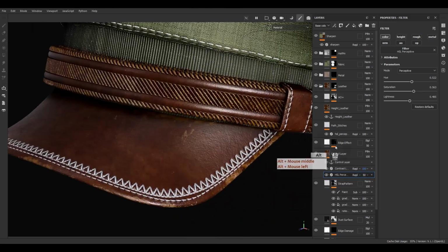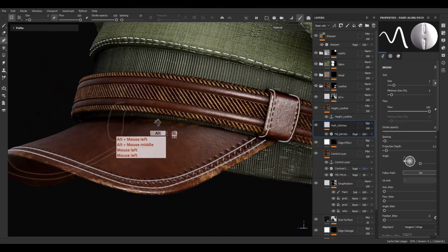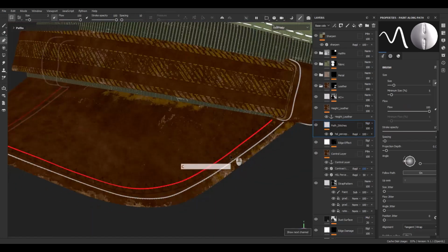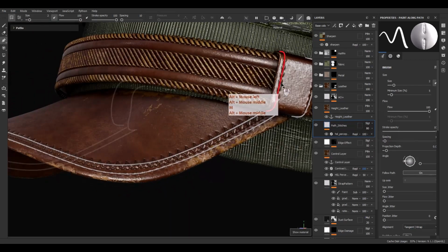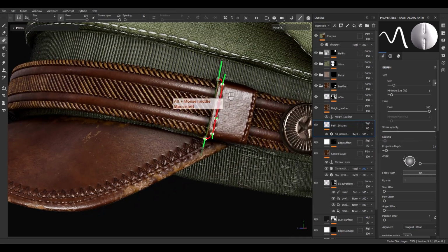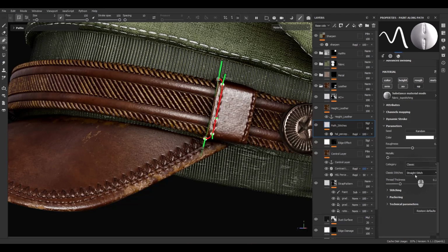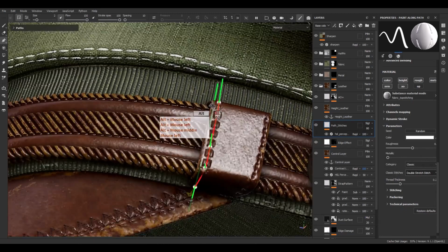And I'm going to use soft light on the blending mode for the stitches. Yeah, it's so much better to have something like this. Okay, and we can decrease the opacity amount to something like 80. That's it. And for this kind of stitches over here, I can change the stitching type or class to double, because in this way,